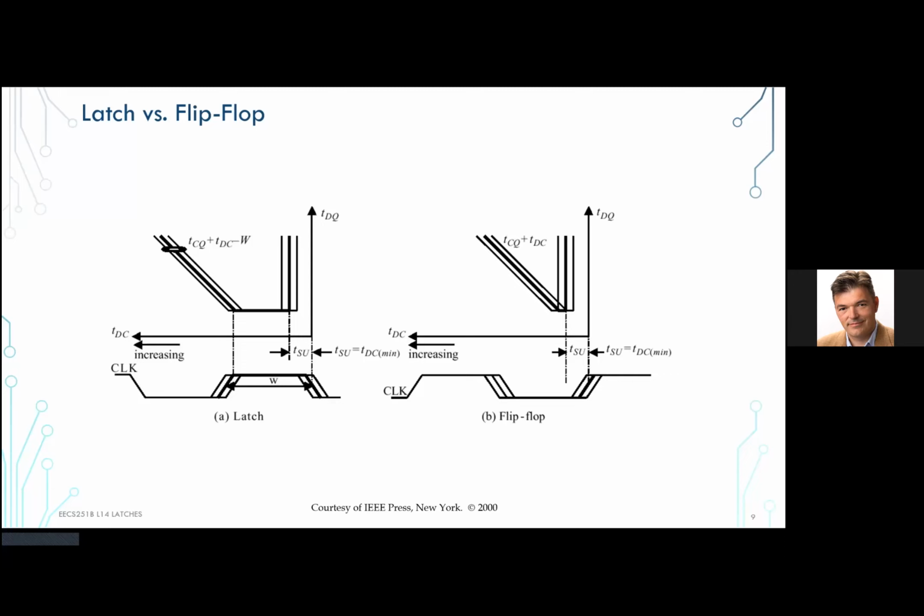The minimum penalty on time is the time that it takes me if that data arrives just on time, together with the clock edge. What is the overhead of having a flip-flop in the system? That is essentially the clock to Q delay. But if data arrives earlier, it does not get any reward for arriving early to a flip-flop. It basically consumes all of the slack on the flip-flop. So there is an added penalty when you just linearly add any separation between data and the clock to the penalty of having that time.